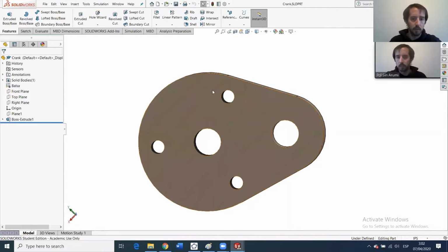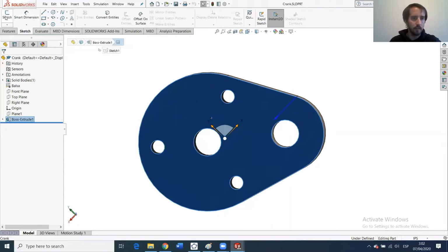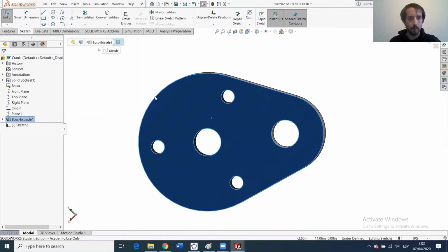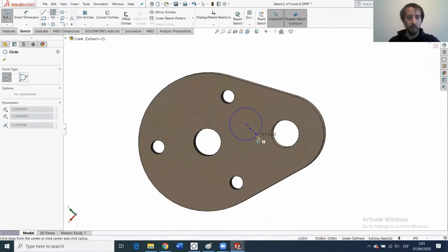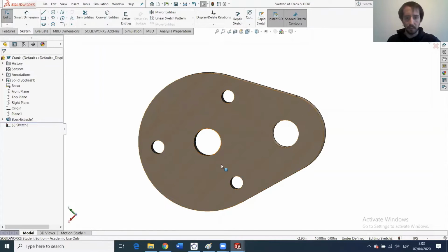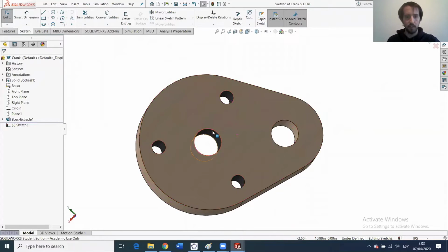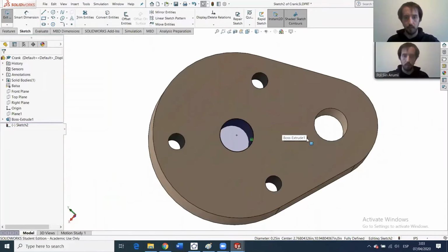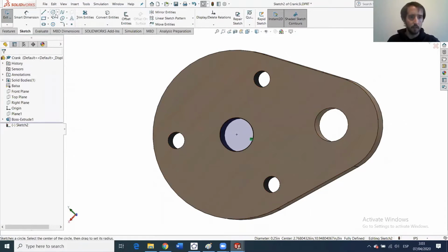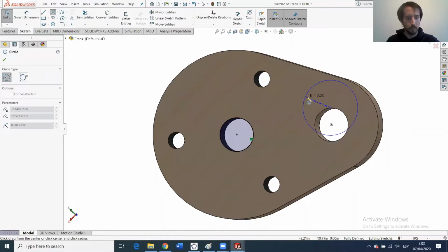Yes. So we're going to create a sketch. And what we're going to do is, okay, so I can build something like, for instance, here. But sometimes the things that I want to build are already in the sketch, right? I mean, they're already built. So in this case, I want this circle and this other circle. But as you can see, right now they are not in the sketch. But if I select the circle and select convert entities, now you can see that the circle has appeared. And I can do the same here.